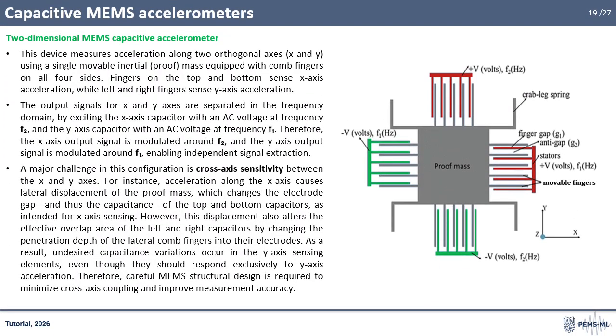As the main advantage, capacitive MEMS accelerometers are largely temperature insensitive, so compensation is usually unnecessary, and they can operate reliably at elevated temperatures exceeding 125 Celsius degrees. With no mechanical contacts, they avoid friction and hysteresis, offering excellent stability, repeatability, and near-zero energy consumption. MEMS technology also allows close integration of signal processing circuits on the same substrate, reducing parasitic capacitance and improving measurement accuracy. The main limitation is high output impedance, which requires impedance matching circuits.